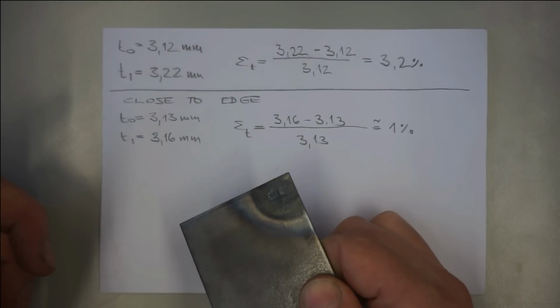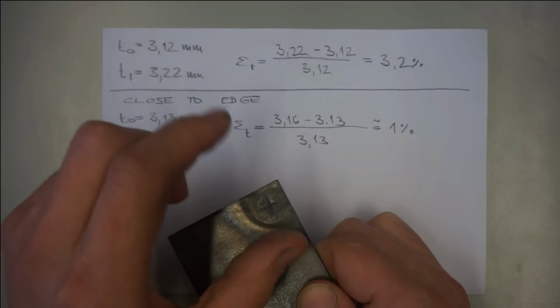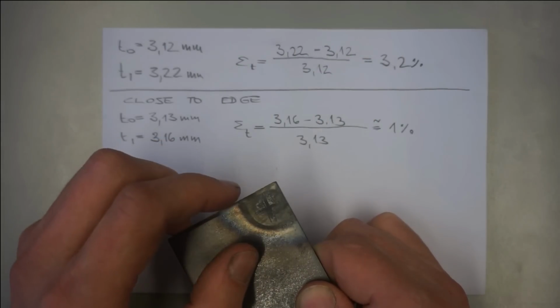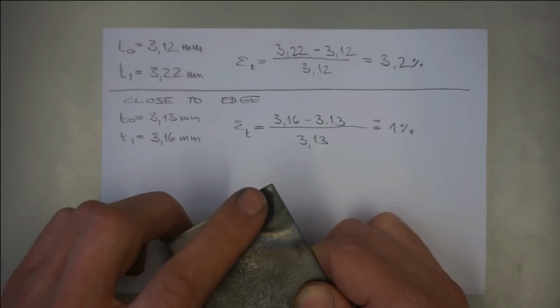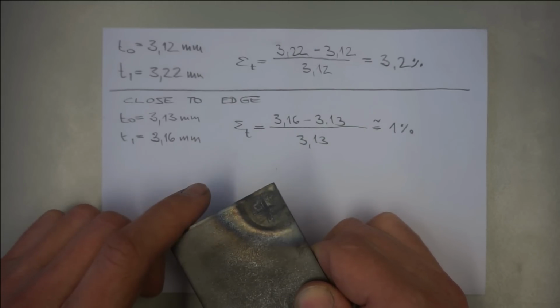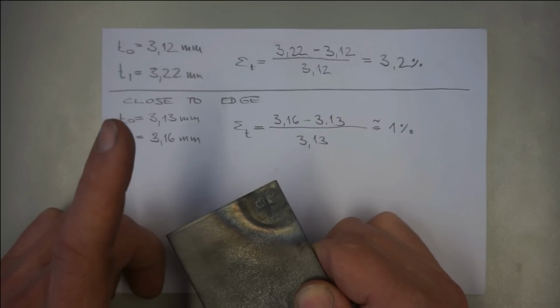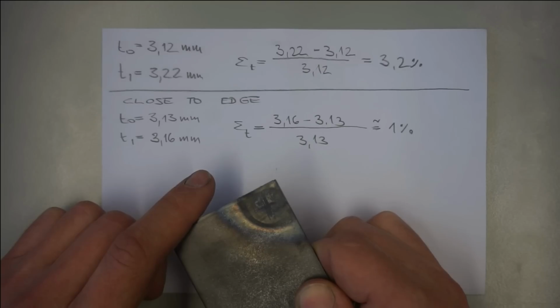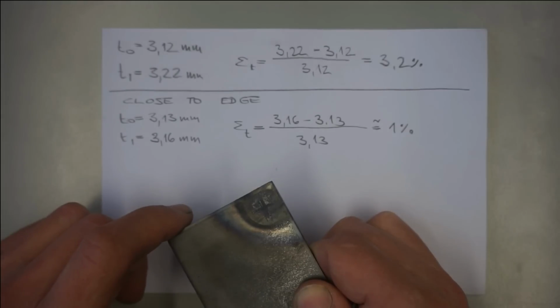But why do we find less thickening here? Right, it is because the thermal expansion of the heated spot wasn't constrained much in plane of the sheet, since it is located so close to the edge. This is the second essential observation about welding distortion. Since thickening correlates with distortion, we keep in mind that less constraining of the heated spot's expansion gives less distortion.